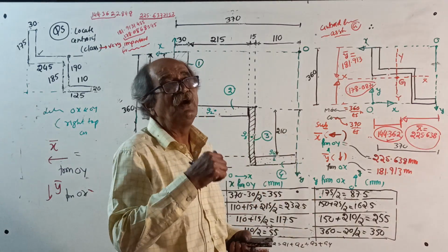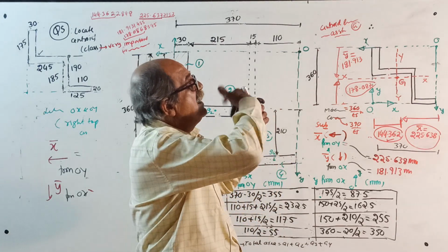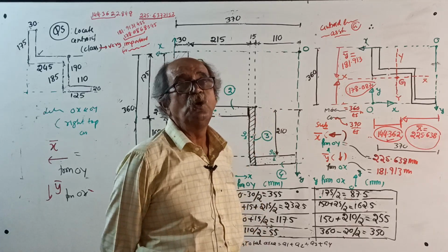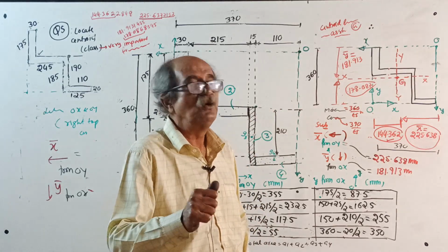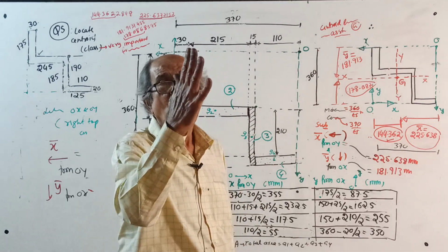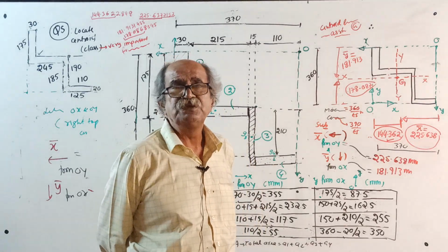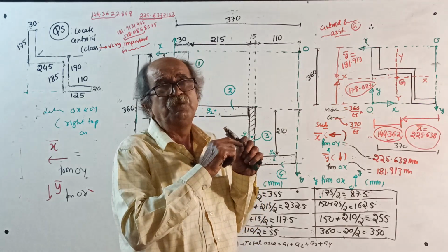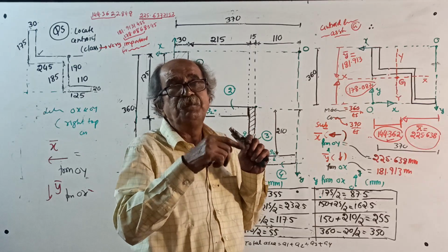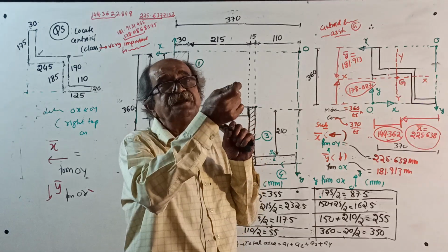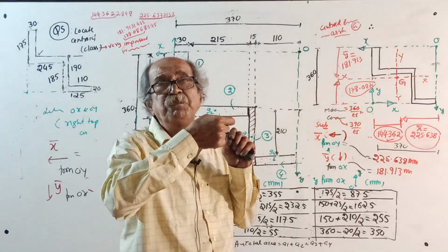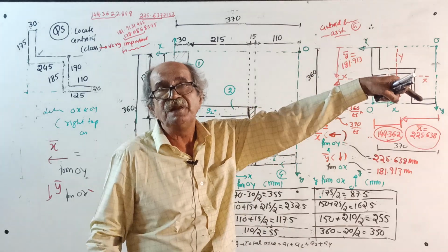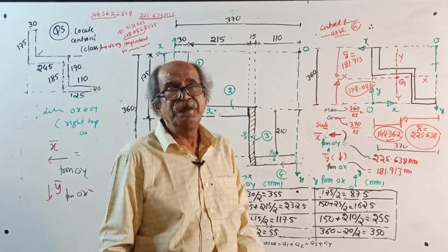I said, oh, tell me, what have you done? He told, sir, this reaction in this text, okay, then minus 2/3 of base into height. Oh, 2/3 of base into height. Who told you? Sir, formula. No, that formula of 2/3 of base into height is valid only for a parabola, for a simply supported beam with UDL, if you consider the BMD from support up to center. If it is an intermediate point, up to an intermediate point, you cannot do it. Cantilever, you can do it. The reason is there. You have to go by integration.